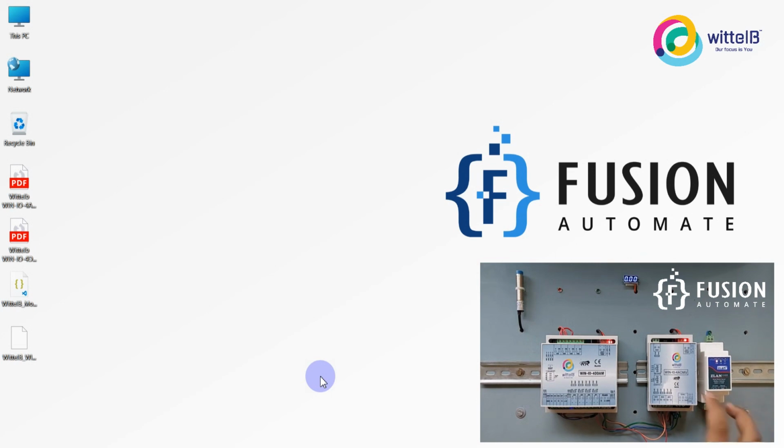So we are going to connect with this Modbus IO card from the KEP server, and we are going to fire this LED from the KEP server only. We are going to change the output voltage from the KEP server. Everything we can do in the KEP server.